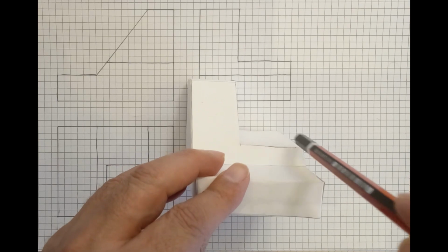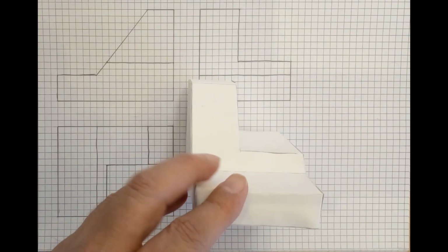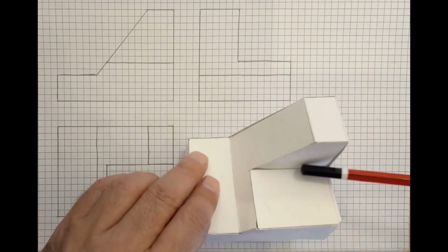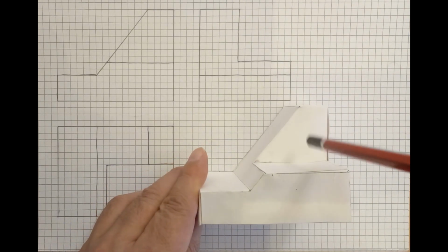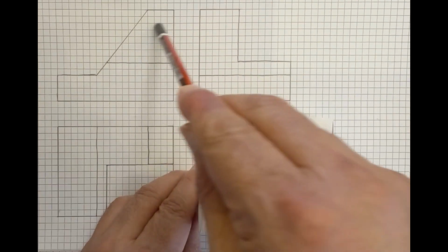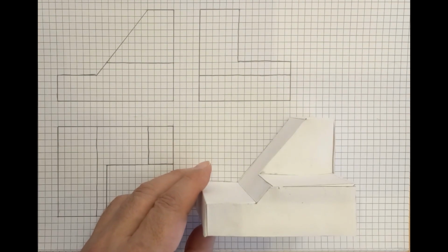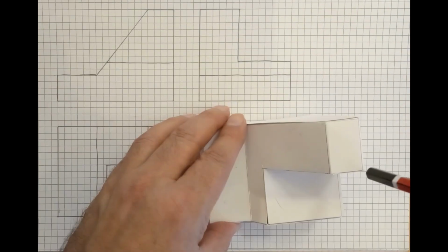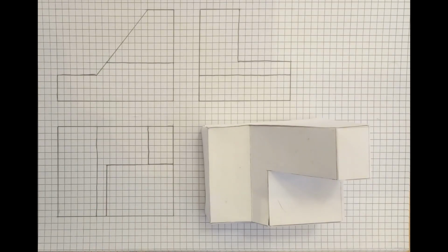The same in the left side, it will appear as a line, this line. Another surface, this one again, is a vertical surface, so in the front view, my side is perpendicular to this surface, so it will appear in its true shape and true dimension. In the side view, it will appear as a line, this line. In the top view, it will appear as a line as well, this line.